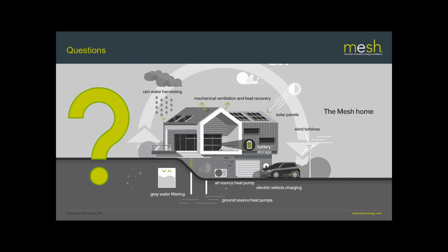So Natasha's asked, can MVHR also supply summer cooling? There is a system that Zender offer where you can put a small cooling unit into the supply ducts for the MVHR. However, I would caution about thinking of it as being a sort of air conditioning type system, because the amount of air that MVHR supplies is much smaller than an air conditioning system will move.